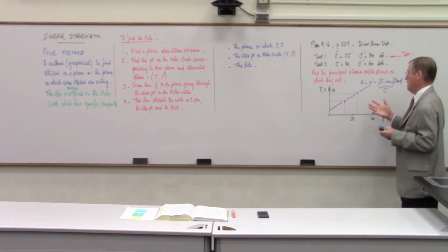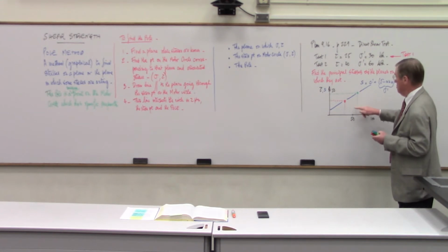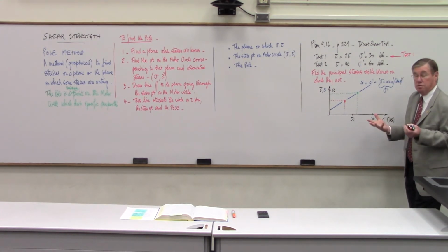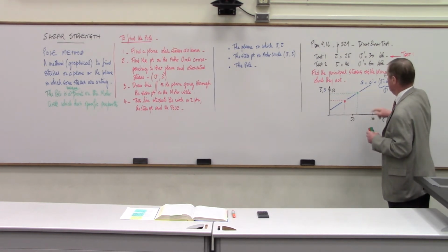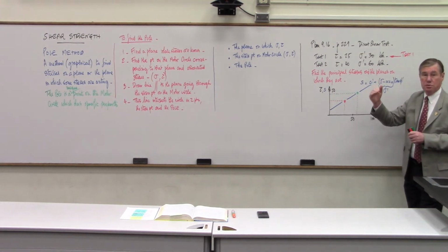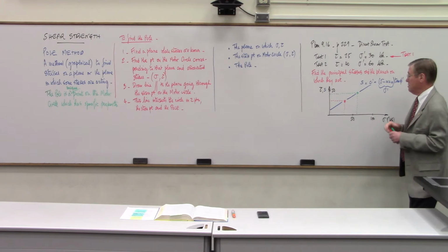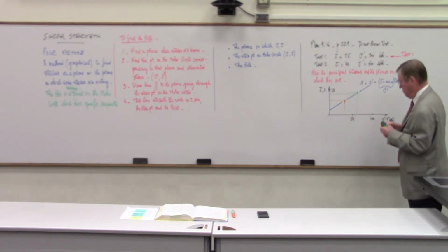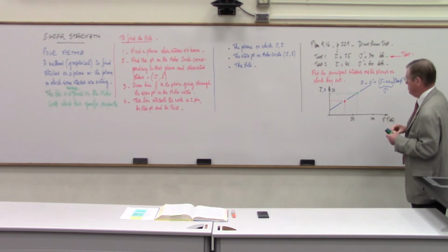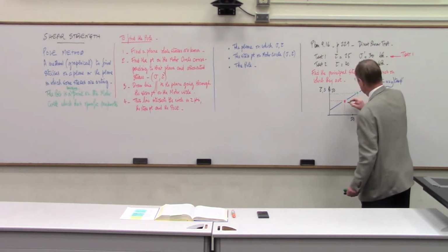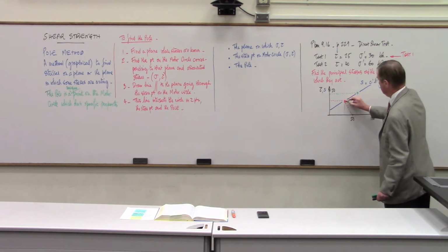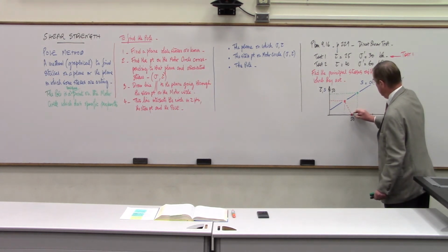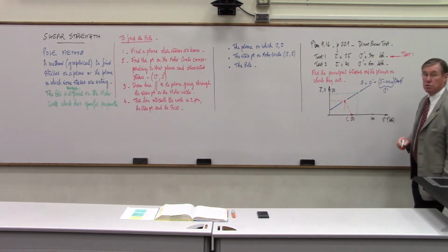shear test? This Mohr circle cannot be under that blue line, because then we wouldn't have a failure anywhere in the sample. That circle cannot be intersecting the blue line, because we'd have some stress points that are beyond the failure line, and they would have failed before they got there. So therefore, the Mohr circle has to be tangent to the blue line. So what we do is we take the perpendicular to that blue line going through this point, and that gives us the center of the Mohr circle.